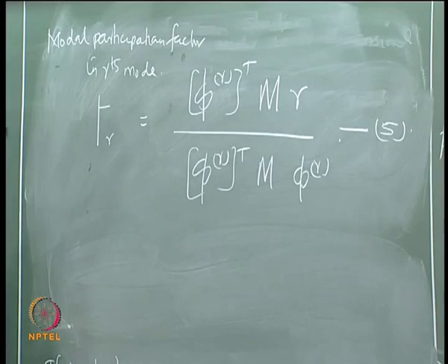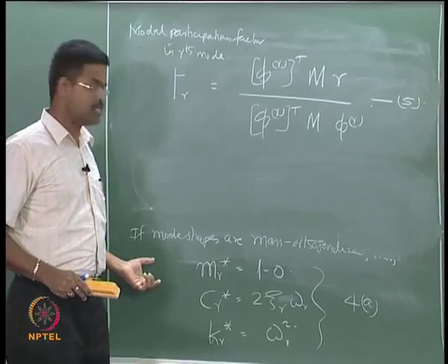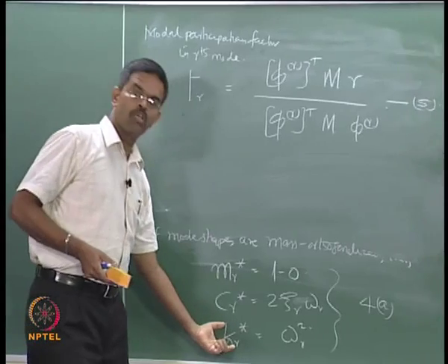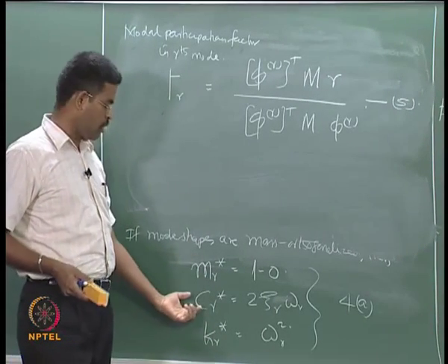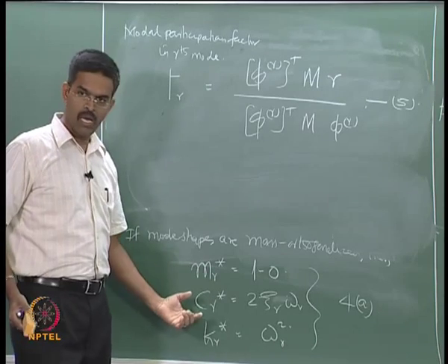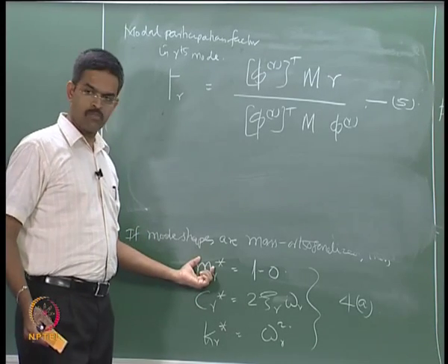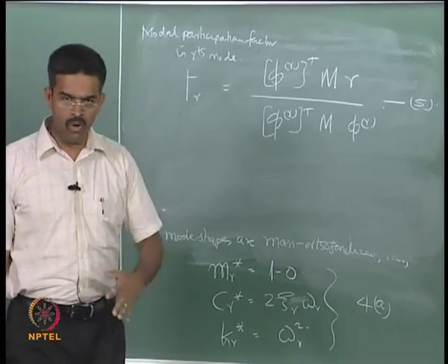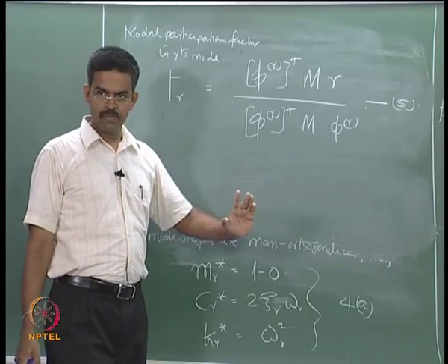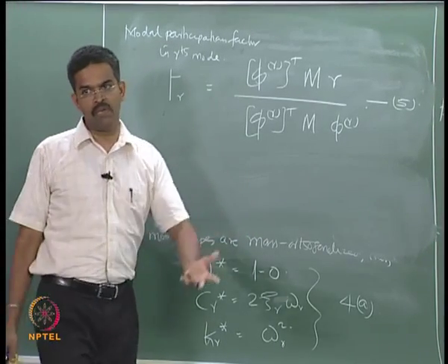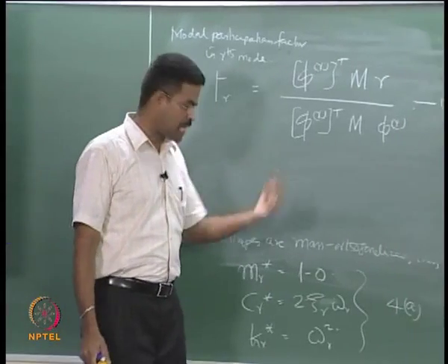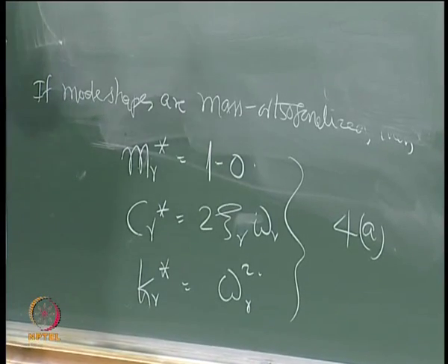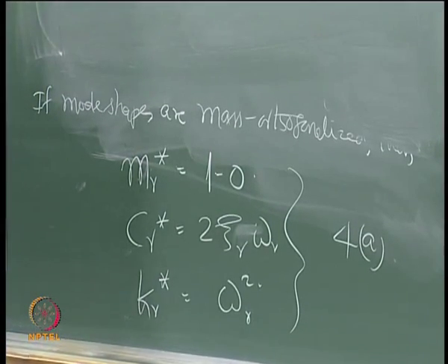Why are we talking about mass? Because mass is the major source of contribution, giving the inertia force to the system. I am not talking about the restoring force. Of course, that depends on these two, so we do not talk about it, because there can be systems which are undamped also. But mass gives the inertia force, which is predominant for dynamics. We already discussed that even though the response and the excitation force are time variant, if the system does not have a substantial mass that can produce significant inertial force, we do not do dynamic analysis.